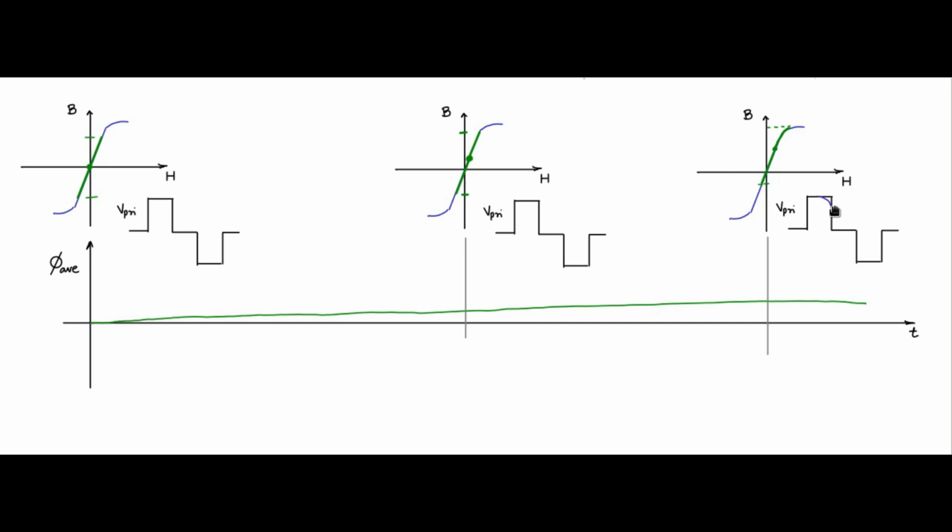So this drop in the induced voltage of the primary can cause a high inrush current, because Vi is fixed, constant, applied as the input. The primary is showing a lower back EMF, and the difference in the voltage Vi minus this lower back EMF will cause a large inrush current, and which can blow up the devices. And it is against this problem that we have to protect.